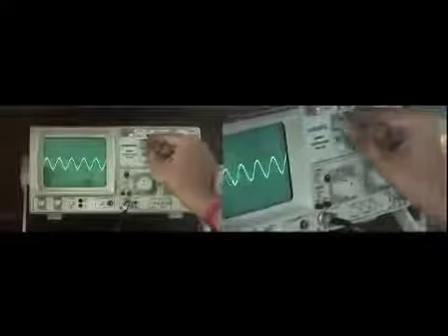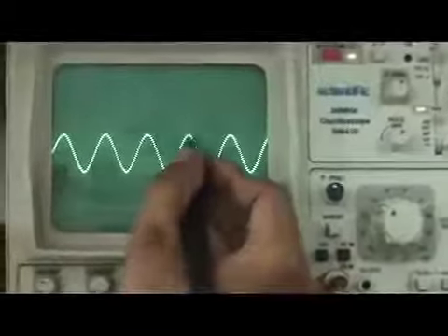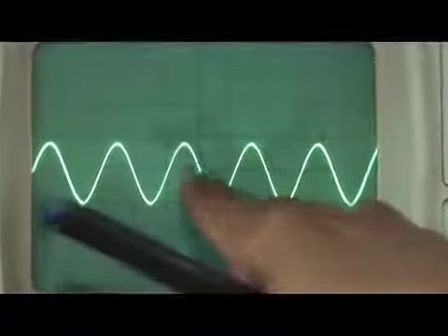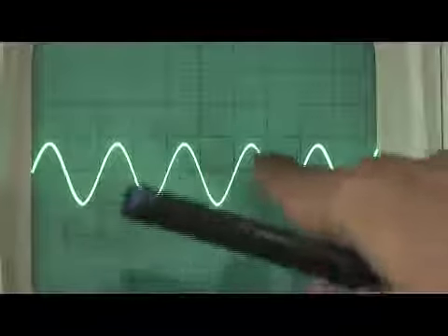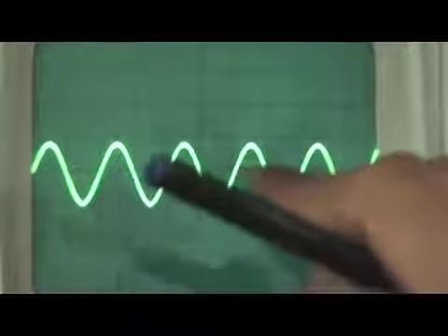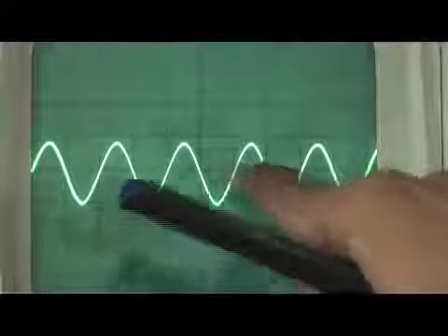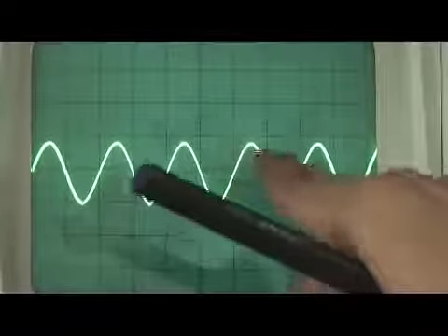Next we move to how to calculate the frequency. Again make it ground, bring it to the center of the line, release the ground, and set this y-axis in such a way that you can easily count one cycle. If I set it here, from this point this is my one complete cycle till here. How many blocks does it require? It requires 1, almost 2, or let us take it as 2. So it is 1 block, 2 blocks. To complete one cycle it requires 2 blocks.